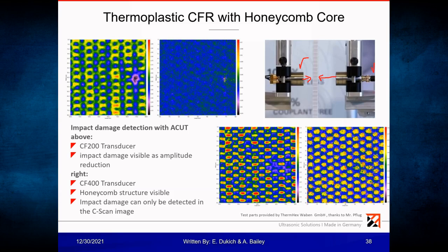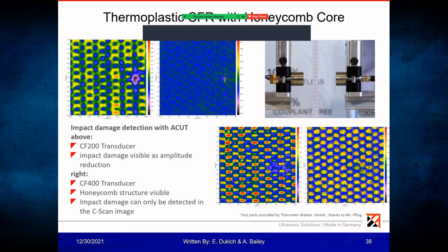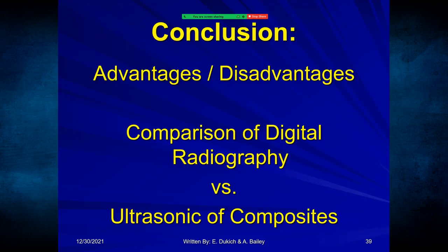So we have a C-scan, remember the top plan view image, of a good composite on the right, and a composite with a flaw in it on the left. So we can find these very small discontinuities using air without water. And that way we can avoid water entrapment.